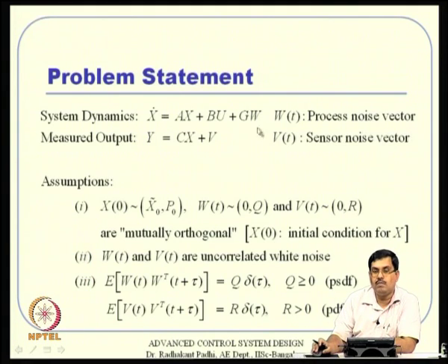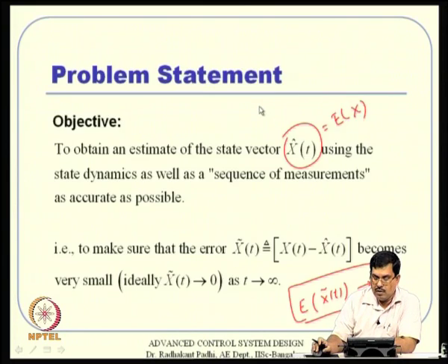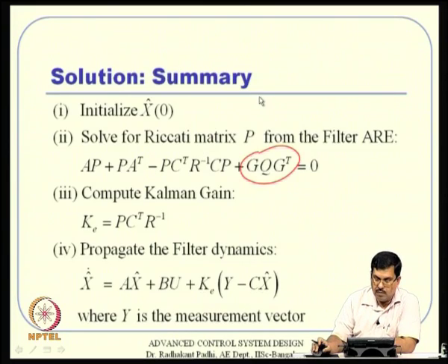In other words, the LQ observer is also like a Kalman filter, where we are assuming that G is actually an identity matrix. That may not happen, of course. The W, like a control input, may not alter the x dot directly, by the way. It passes through an influence matrix anyway, G. So, if you assume that G is actually identity, then it is nothing but an LQ observer actually.